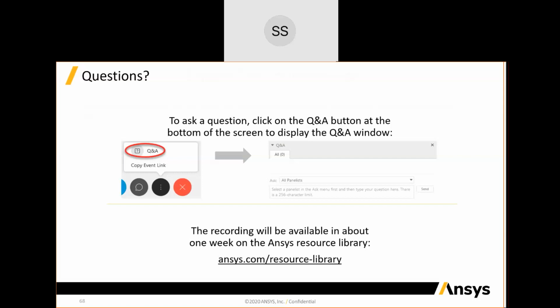And then you can import this into optiSLang, very similar to the steps that I had shown you here today, where then the input would be geometry parameters defining maybe some of the via definitions, maybe aspects of the trace width, or maybe there's some smart ways that you can set up the routing of the channel. But those inputs are controlled by optiSLang, and then the output could maybe be something like the eye width or the eye height, and then we could optimize for that, or maybe look at how manufacturing tolerances could play a role in impacting the eye opening.